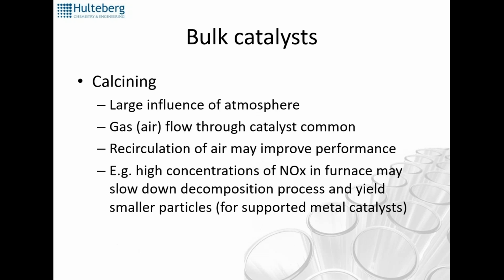But in calcining, there's also a large influence of the atmosphere. You see having a gas flow, for instance air, flowing through the catalyst is really common, and it not only improves your transfer of the heat from the gas to the catalyst, but it also influences the calcination environment.